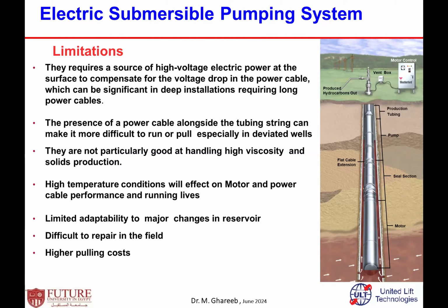However, temperature is also considered one of the limitations for the cable and the motor, because the motor itself generates heat when it's running and usually requires some cooling. If there is no good cooling and the bottom hole temperature is high, this can affect the motor's performance and running life.